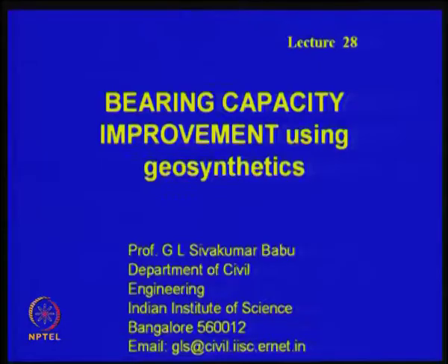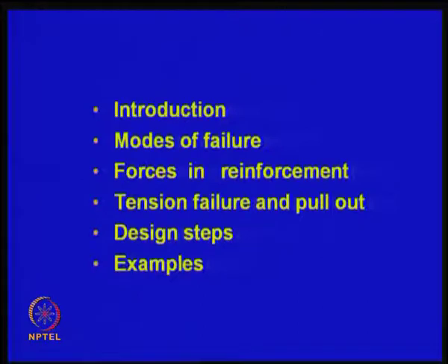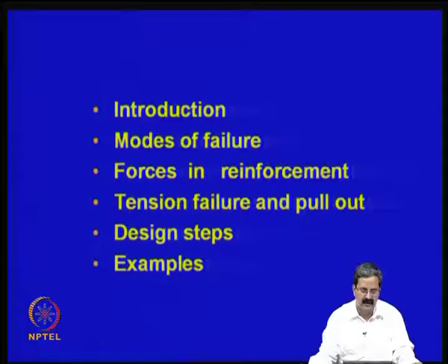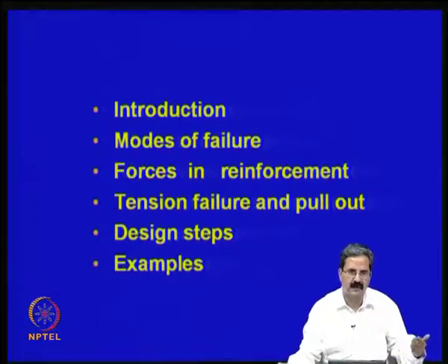Today we will be talking about improvement of bearing capacity using geosynthetics. The problem of bearing capacity is very important in geotechnical engineering. When the applied loads are more than the existing resistances, we know that the factor of safety is less than 1. But in some cases, you would like to improve the bearing capacity, to increase the factor of safety. For example, in a present case it could be 1.3, and you would like to make it 3.